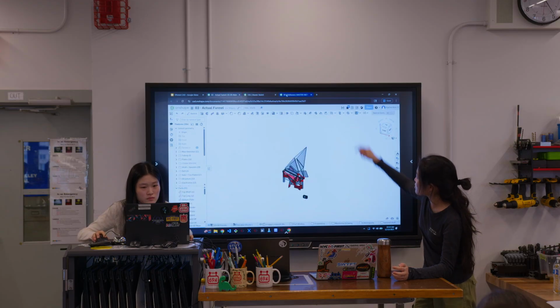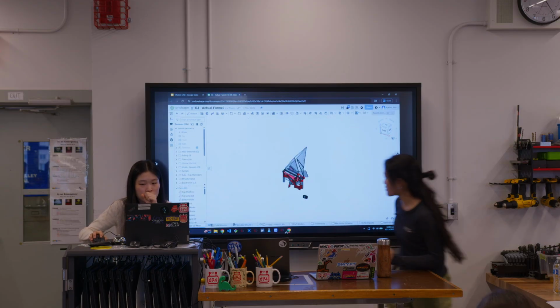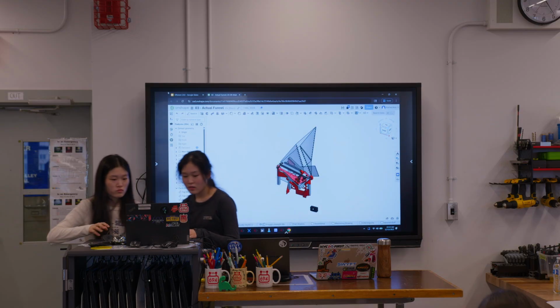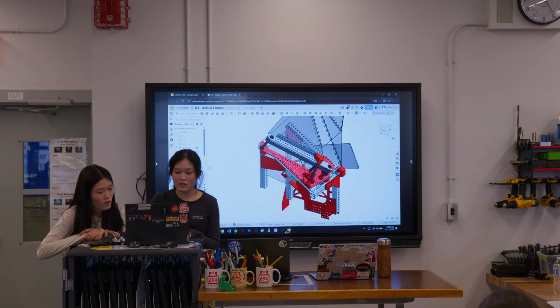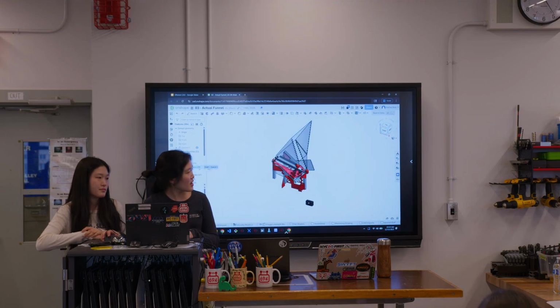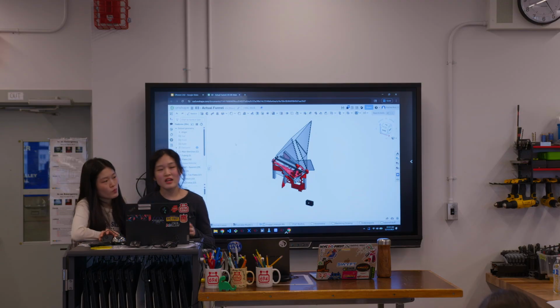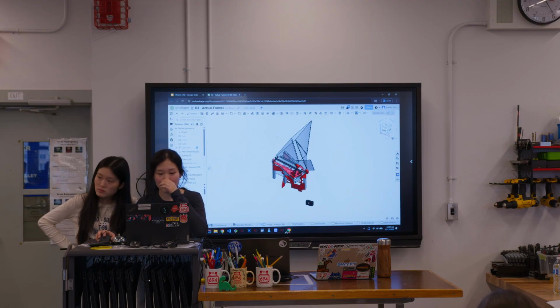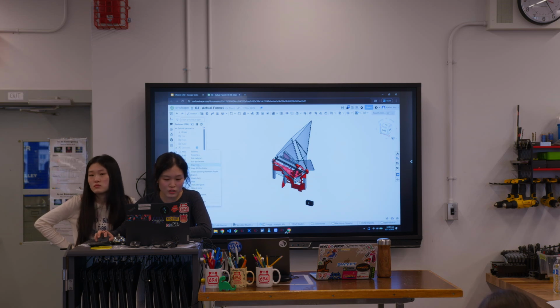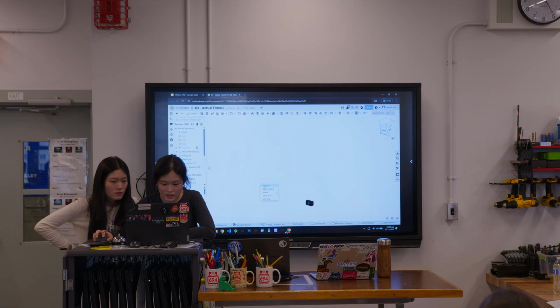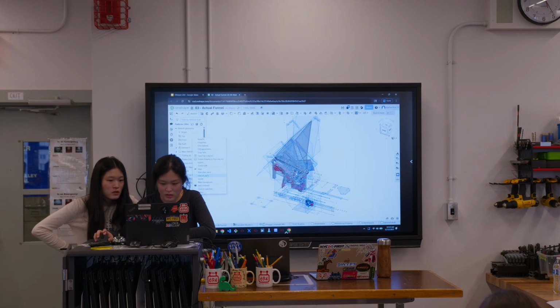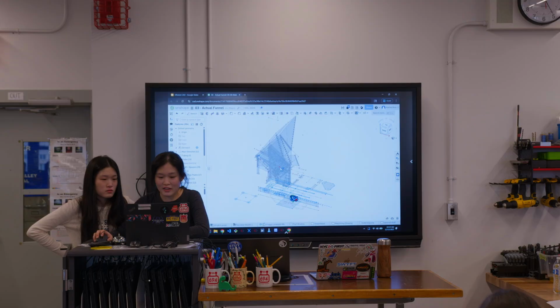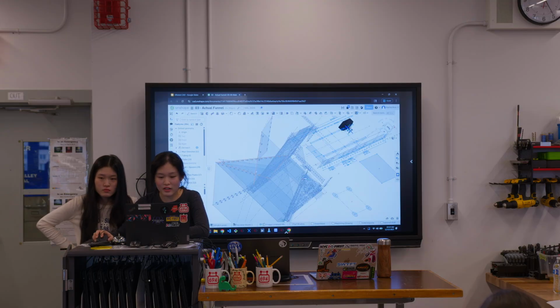Okay, oh yeah, it did load. So this is the part studio, not the assembly, and it kind of does look like the assembly, and that's the whole purpose of it. Since you create a robot master sketch and layer on a mechanism master sketch, you'll have all the sketches related to it in their physical place in three-dimensional space. If I hide all the parts and hide all the planes, you see how all the sketches form to make it look three-dimensional.